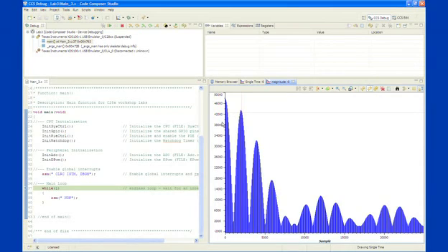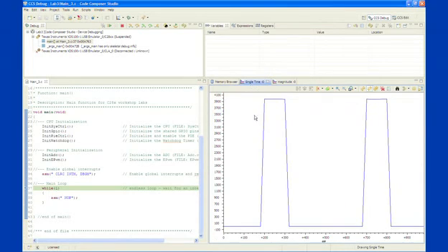Next thing we'll take a look at will be using the real-time emulation features. So let's switch back to our single-time graph window. This real-time emulation is a special emulation feature that allows the windows within Code Composer Studio to be updated at a rate up to 10 Hertz while the MCU is running. And this not only allows the graphs, but all the windows, the watch windows, the memory browser windows, to be updated as well. And it allows the user to make changes in the watch windows and see how those changes affect the MCU behavior, or the processor behavior itself.